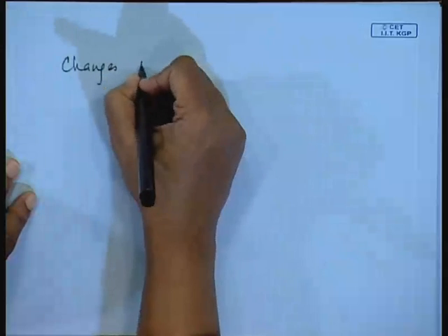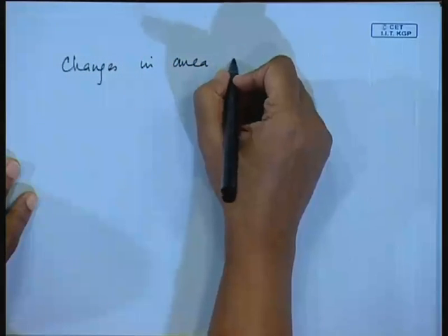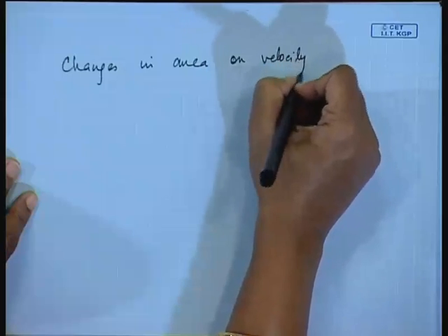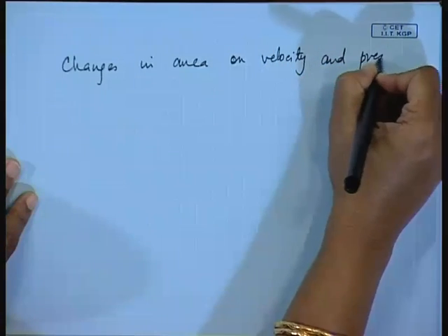We will be starting from the basic energy equation, the final form that we had derived in the last class, from where we got that the enthalpy head and the kinetic energy head remain constant for an adiabatic isentropic situation. So, from there we will start and see how area changes affect the compressible flow cases. Okay. Now, an area change changes the velocity and it changes the pressure